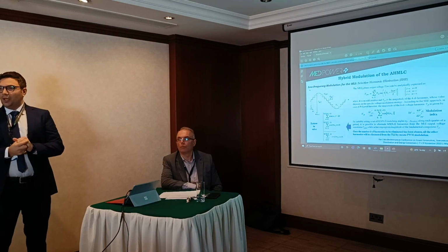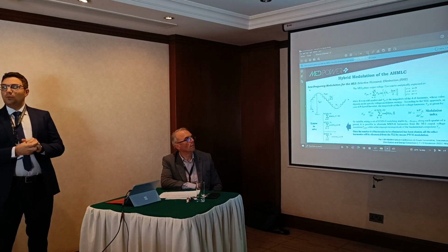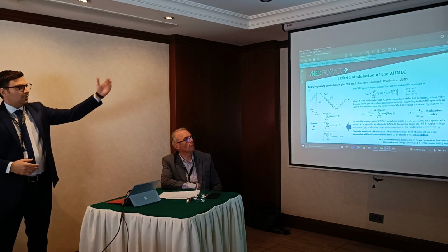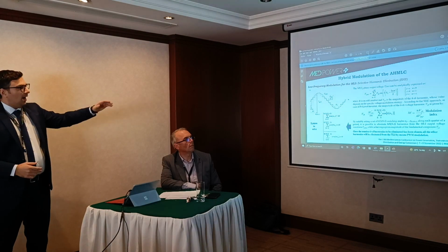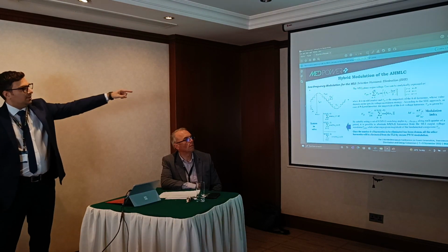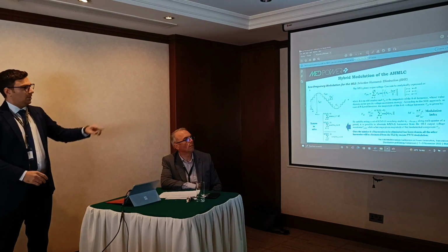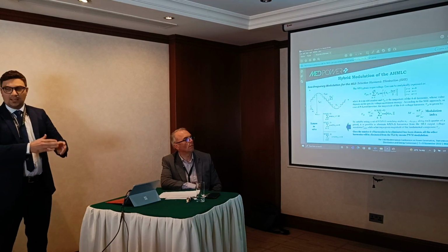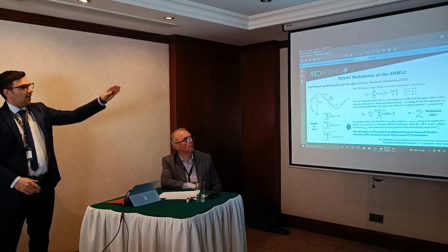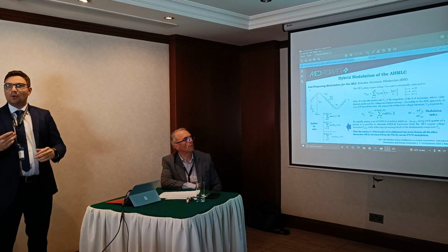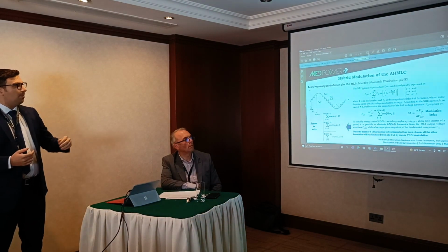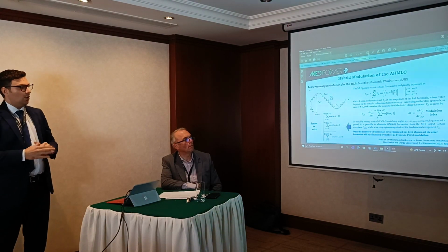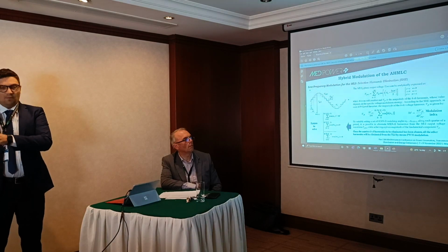About the hybrid modulation, low frequency modulation is exploited in the multilevel converter, and we can consider a selective harmonic elimination scheme, in particular a step modulation. In this picture, we can see the step waveform of the output voltage, and it's possible to eliminate a set of harmonics. But in this case, the maximum number of harmonics that can be eliminated depends on the number of output levels. In fact, the other harmonics will be eliminated by means of the two-level converter.